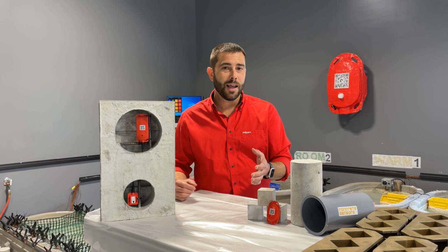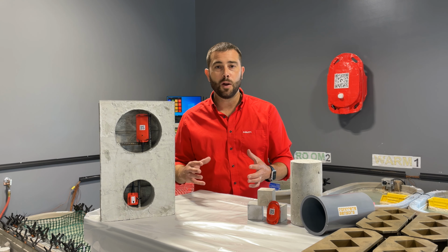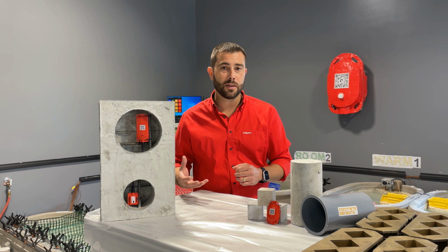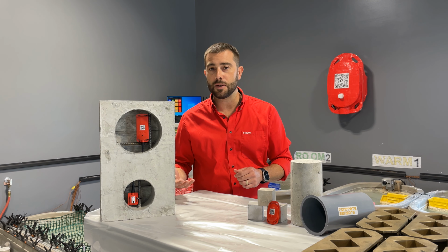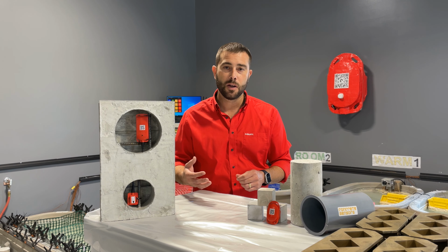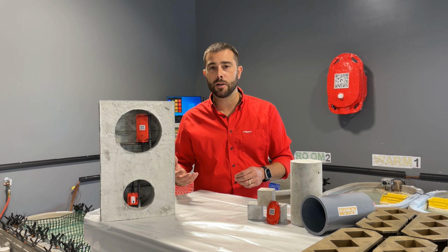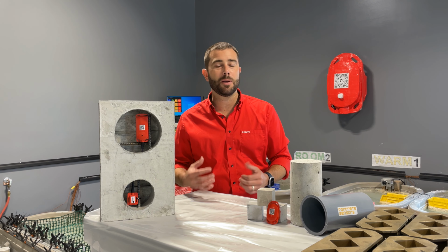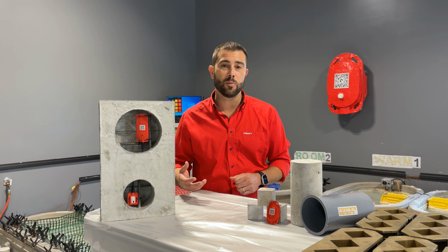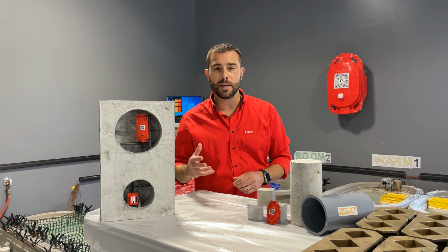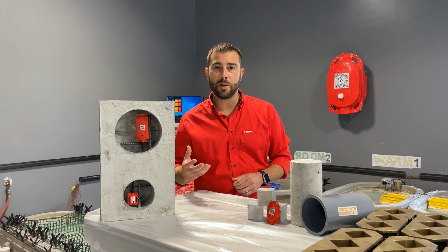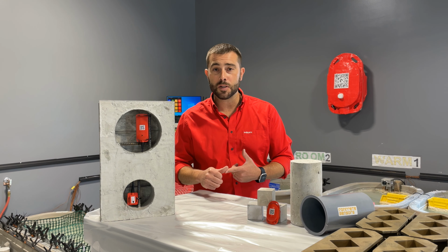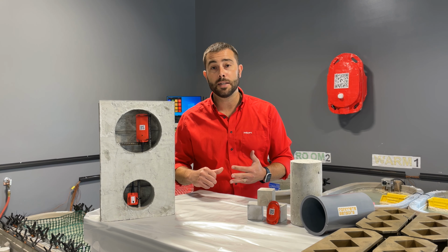Think about that. If we had real-time data to help us make decisions about concrete strength, how would it impact activities such as post-tensioning of tendons, formwork removal and reshoring? Maybe it's the opening of roadways, or when it gets cold in the wintertime, maybe it helps us make better decisions around cold weather protection. All of these are great examples of how we can use the maturity method to impact not only cost, but also quality and safety on our projects.